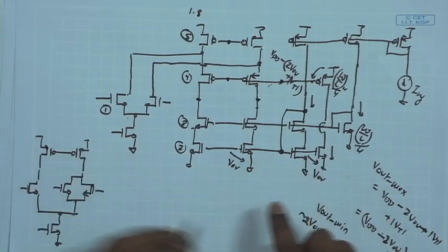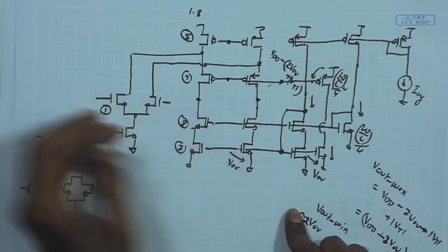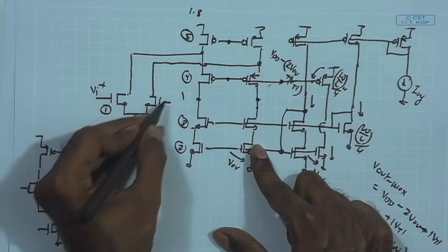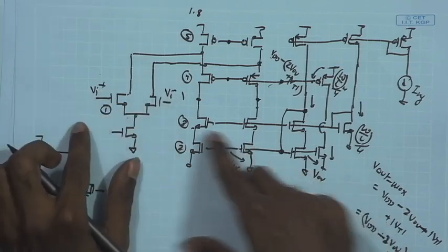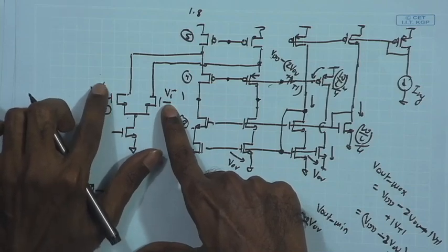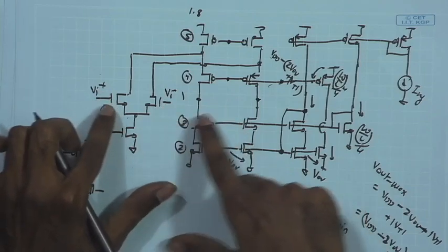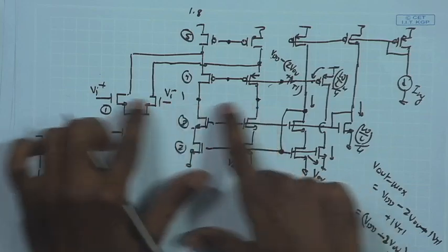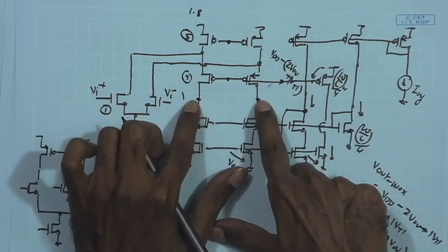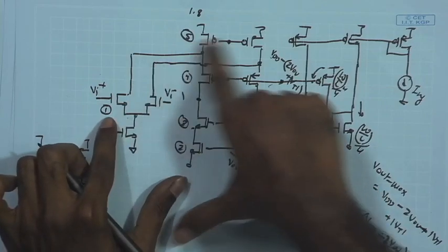And then we have to decide the polarity. So, if I call this say Vi plus and Vi minus, with respect to this, if the input signal Vi plus is going high, we have an overall inversion over here. So, from here to here in this particular branch, we are having VO plus at this point, VO minus at this point. There is an overall inverting gain.